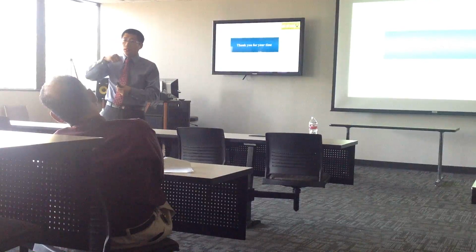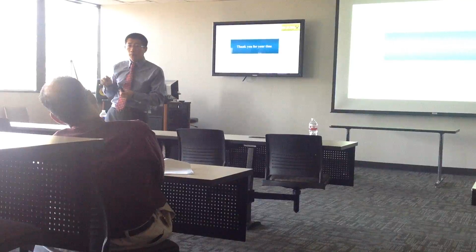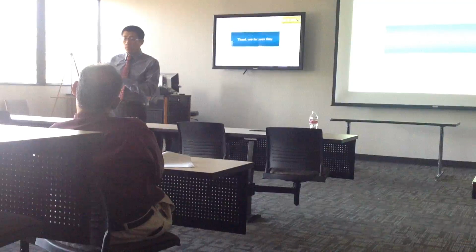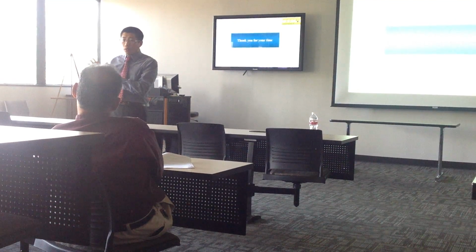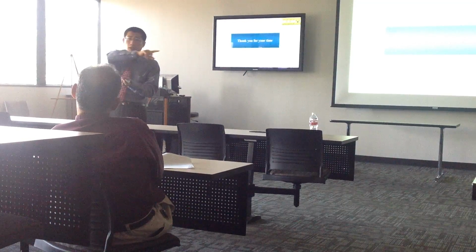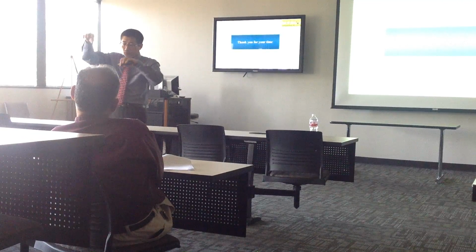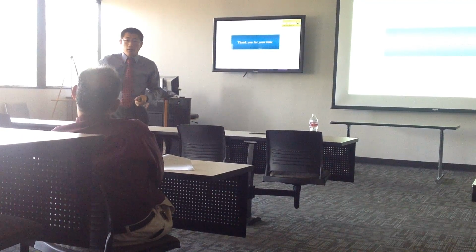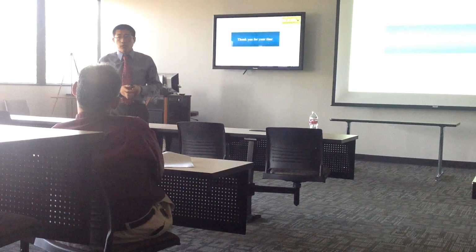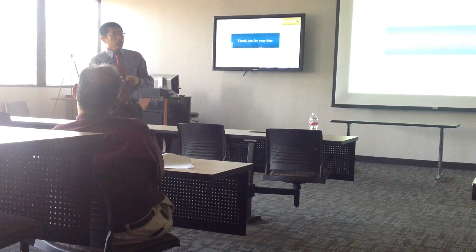At the same time, 5 or 10 years ago, the gamma theta model came. It can predict good parameters for the transition flow, while the SST is for the separation flow. So with the SST gamma theta model, we can predict both the separation and the transition, all the flow behavior. That's a very good model. Most of the time, if you want to make it easy, you just use the SST model.